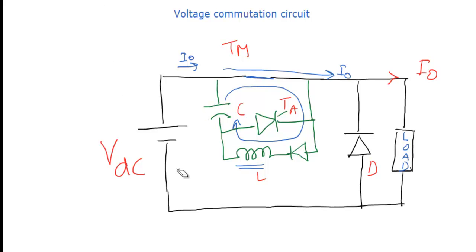In that case, current will actually reach the maximum. Now, in this same path, the inductor will try to discharge. That means it will charge the capacitor. Whatever energy is available with the inductor is transferred back to the capacitor, which gets charged by the inductor in this direction. Current is in this direction. That's why this is the positive plate and this is the negative plate.